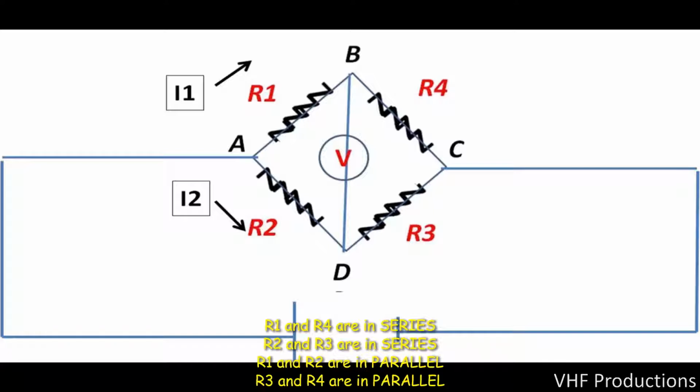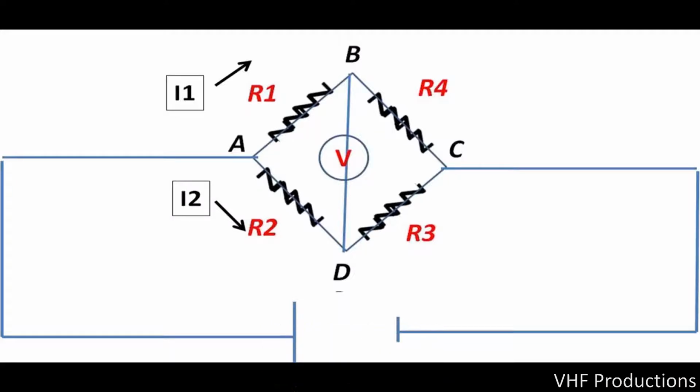To review again, here's a simple Wheatstone Bridge configuration. The four sides of the bridge can each contain a resistor, and those resistors can either be fixed resistors, variable resistors, or the strain gauges intended to be used. In the initial condition of the Wheatstone Bridge, all four resistance paths have to have an identical resistance. So to begin, R1, R2, R3, and R4 are all set to identical resistances.